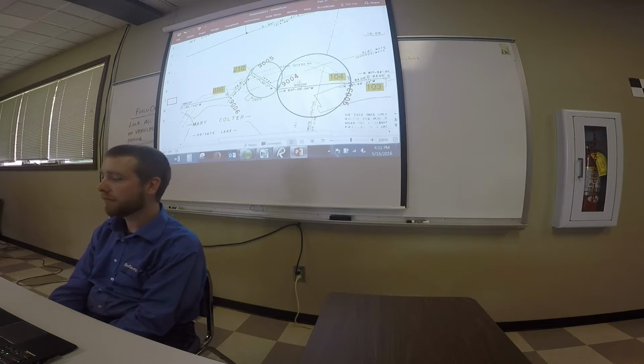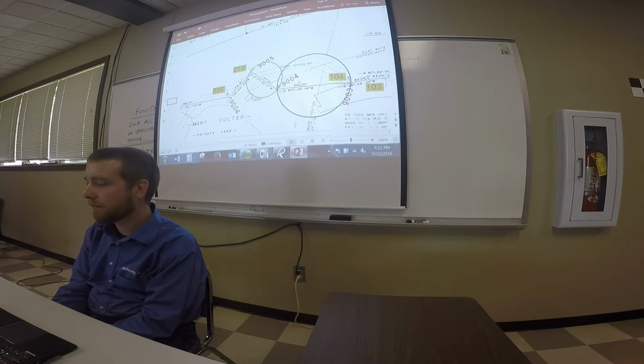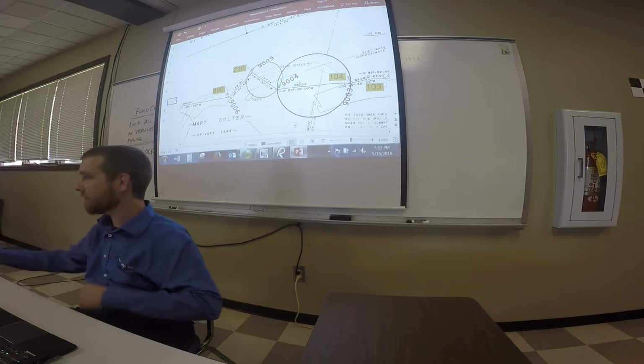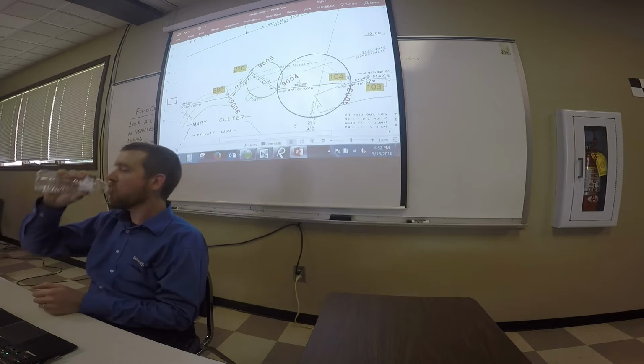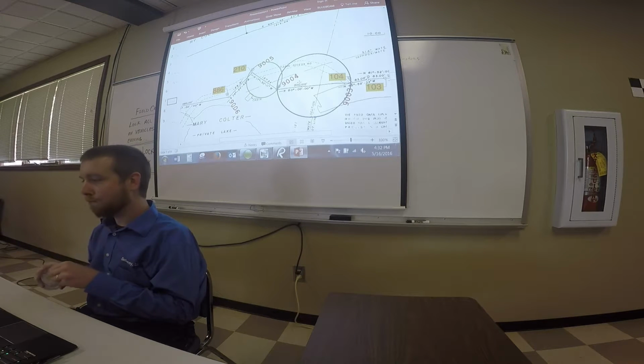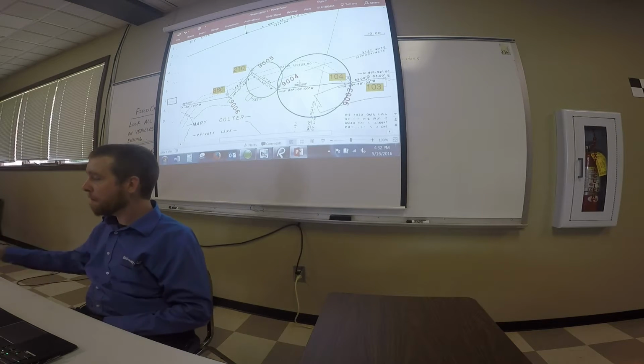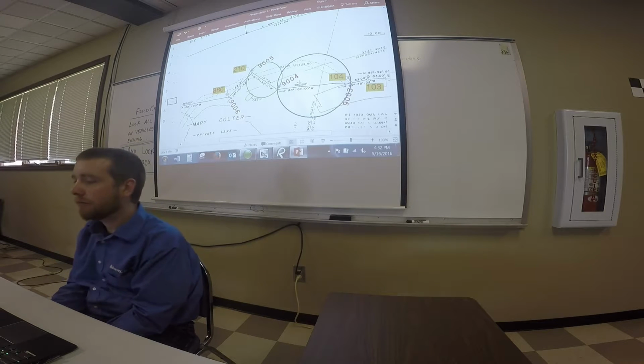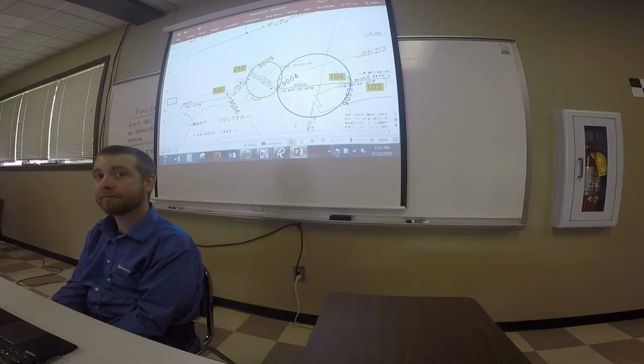Well, you've got a map here that's given to the nearest 100th and degrees, minutes, and seconds, because you've got an accurate map that you've proved closes with the monuments on the ground and the angles and distances that you piped in. You're doing exactly what we do. We just make a judgment call as to which one. And if I recall, there were concrete monuments out here on some of these.